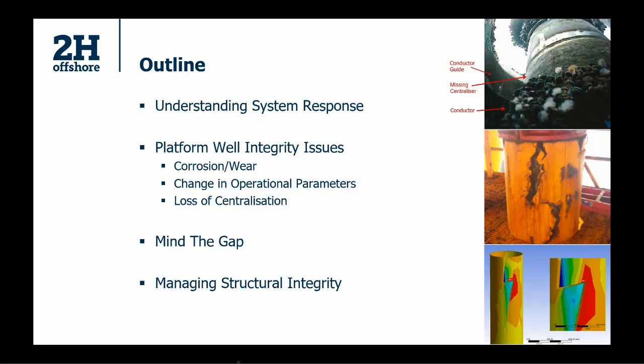That's from an inspection footage where the point of view is looking up through the guide funnel. So the white section that you can see, that's actually daylight. And you can see that there's a high level of marine growth on the conductor, and the bare pipe that you can see with no marine growth is where the centralizer was located. I'll then move on to talk about conductor ownership when it comes to integrity management, and I'll talk about the potential gap that there is in integrity management there. And then finally, I'll talk about the kind of processes that we can put in place to successfully manage the structural integrity.